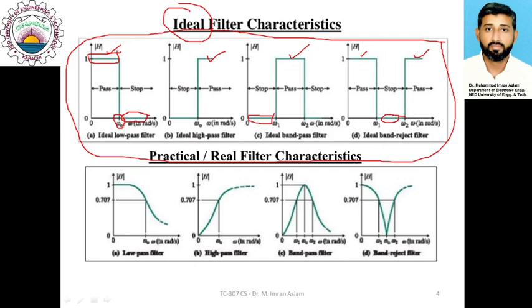However, I want to emphasize that this type of response is actually not possible, because if you look at this response in the time domain through the inverse Fourier transform, you would see that it is related to a non-causal system, and any non-causal system cannot be fabricated practically.